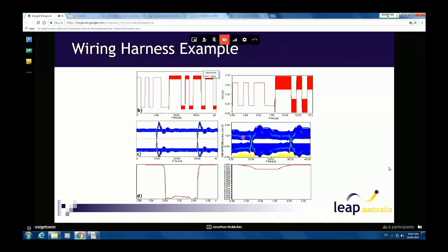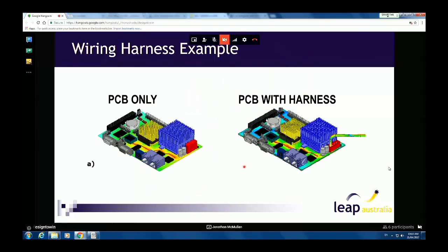The bit stream is basically unreadable, and our error rate increases by 14 orders of magnitude and basically becomes a whitewash. So in this case, the mitigation steps are, if we go back to the picture, we need to either shield this trace through here, or we need to ground it properly. Unfortunately for us, it doesn't specify exactly how they did it, but that's probably the reason why.